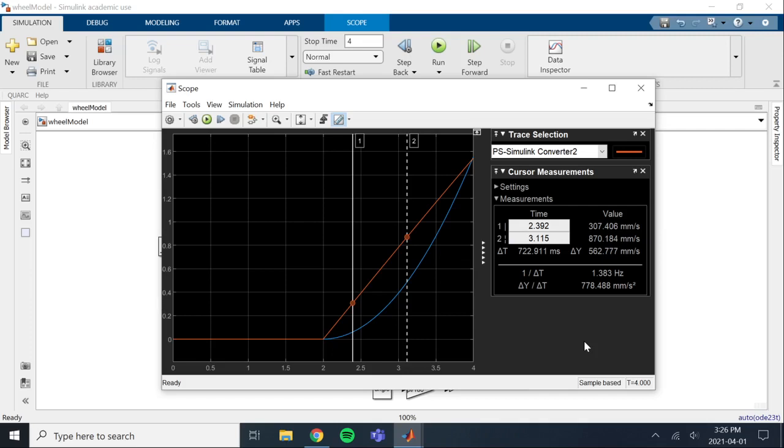So now we are actually rotating this tire with very little slip. We're still getting some good torque. We got some friction on the wheel, so we're actually able to push this Rover and not get any sort of slip or backlash in the gears. So that's why we are moving a lot faster now.